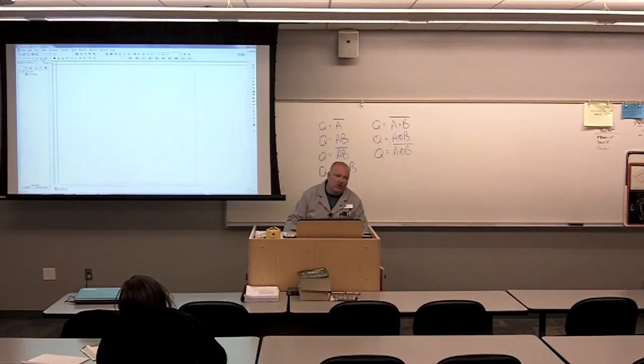TTL were not very prone to electrostatic discharge. CMOS is much higher efficiency, so TTL has all but been replaced in industry right now. As a matter of fact, for our parts kits, we're having a hard time even sourcing parts in TTL because they're becoming quite rare. But anyway, we have the choice of both right in here.